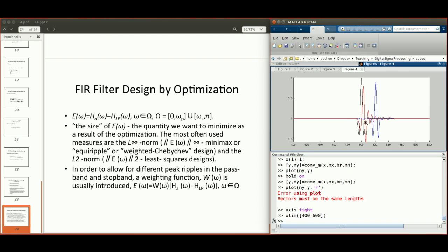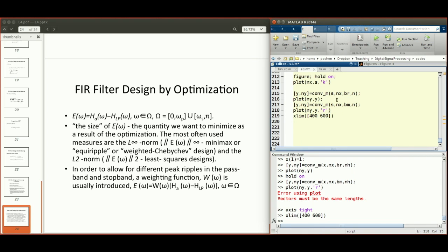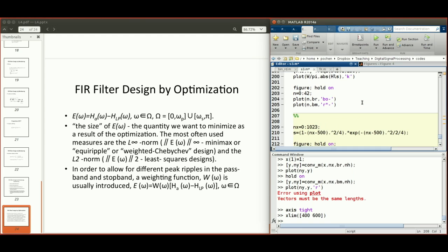But for the linear phase filter, the amount of shift is a lot bigger, right? So if you are trying to pick the first arrival time, the linear phase filter could give you a wrong pick. You might want to pick somewhere here, right? If you're using a linear phase filter. But for a minimal phase filter, the pick is probably the same as the raw signal, right? It's not deviating too much. So that's one example about the different effects of different kinds of phases, and also the FIRGR and FIRPM function calls for you to construct those FIR filters.